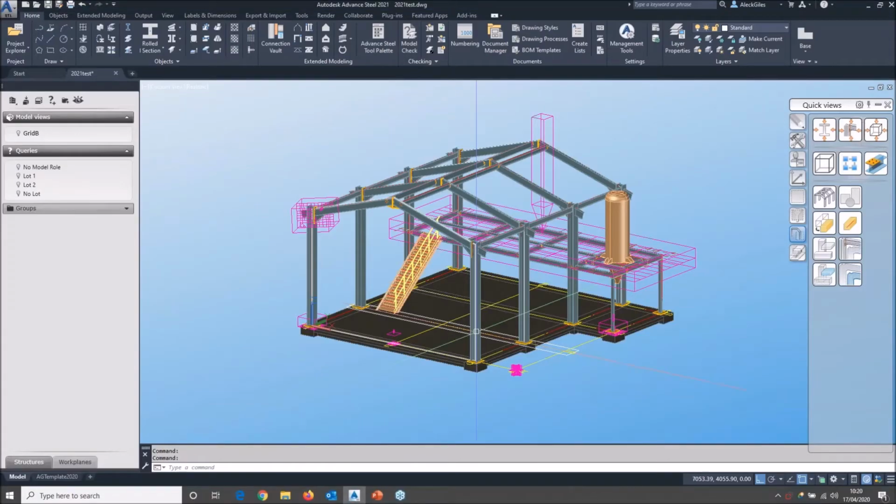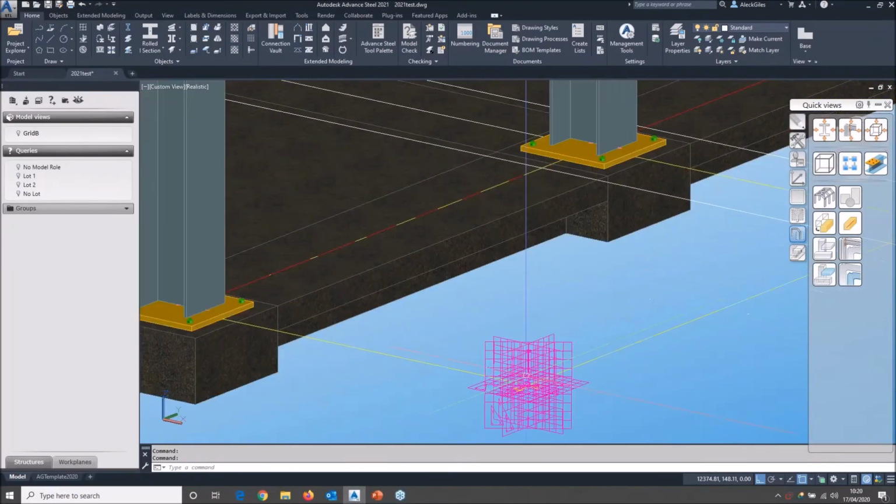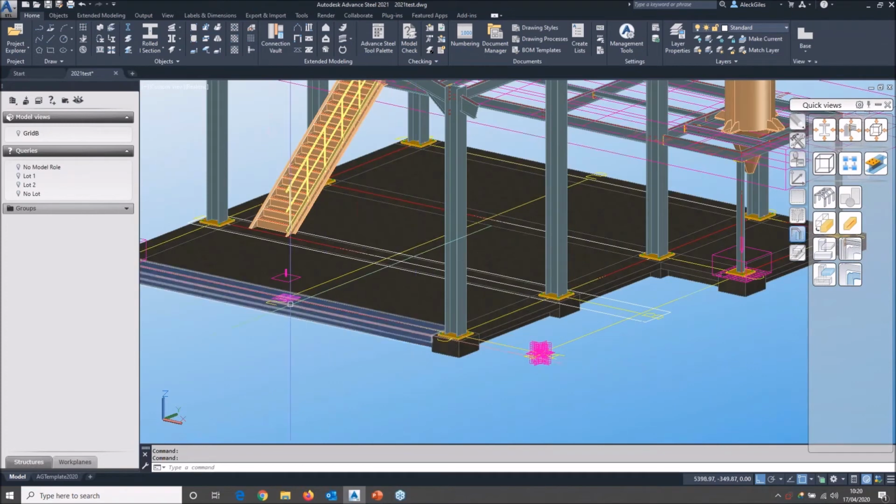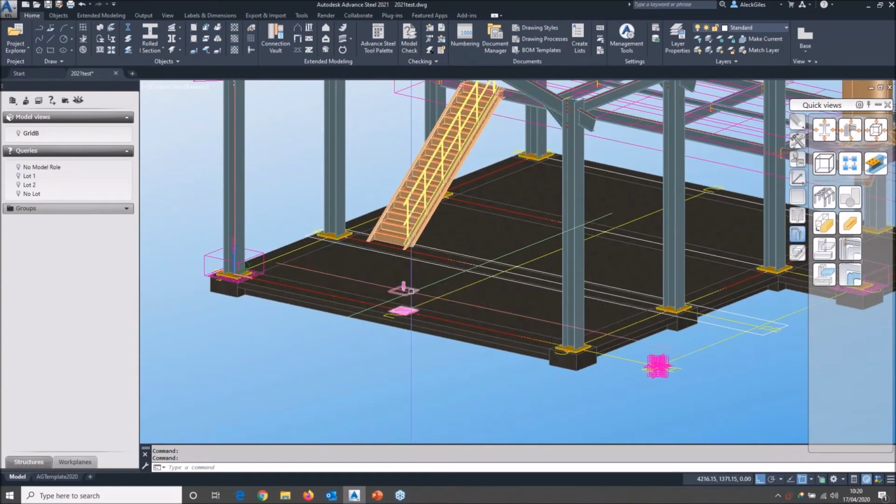So again, looking at my drawing, you can see my overview cameras that are going to do the whole model. I've put them on this free grid point here, so they're easy to see. I can spot them later, I can edit them easily. And again, this one here is my overall foundation. Doesn't matter where it goes in the X and Y direction, only in the Z direction because I'm limiting the depth. But I can see it easily. It's not hidden inside a column or inside another shaded object.